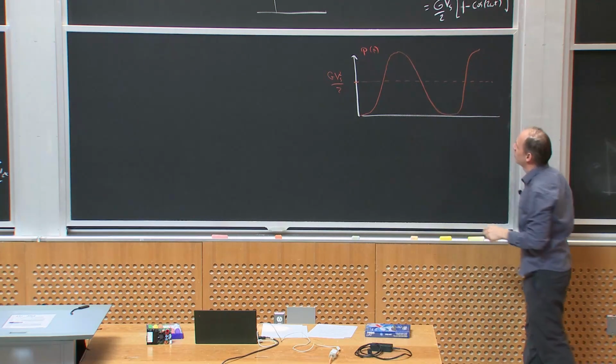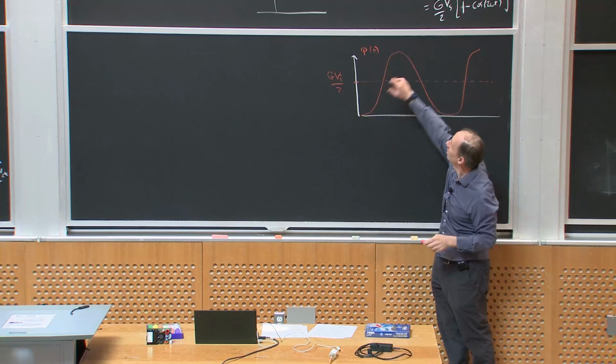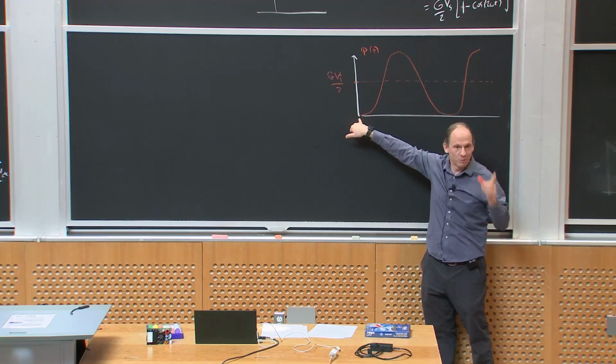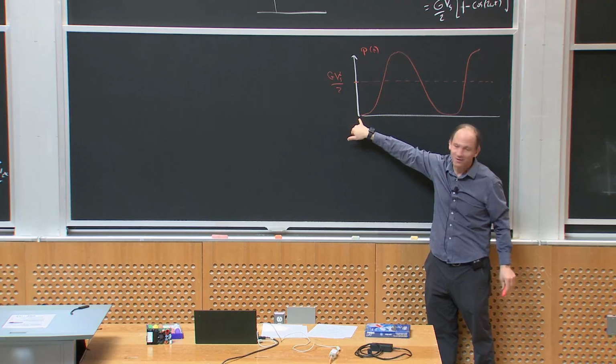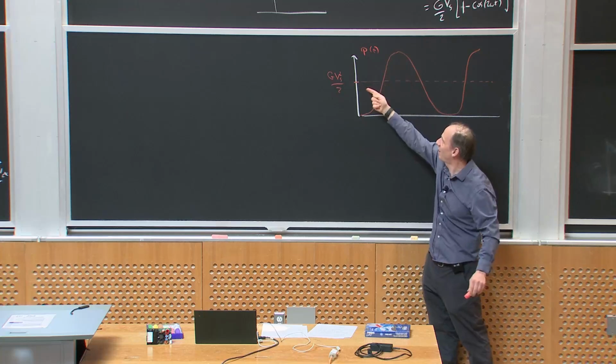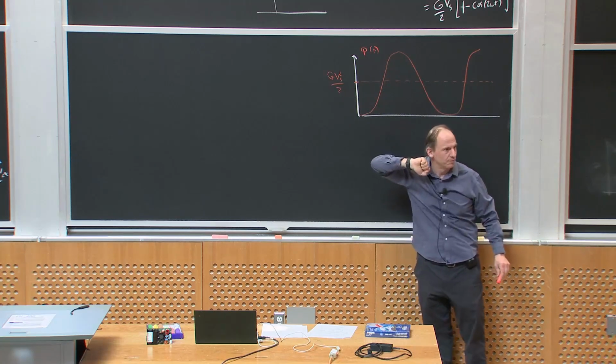That's all that equation says. Why does it pulsate up and down? Because when the line voltage is 0, you're not drawing any power from the line. When the line voltage is really big and the current's really big, you're drawing a lot of power from the line, and on average, you get G Vs squared over 2, okay?